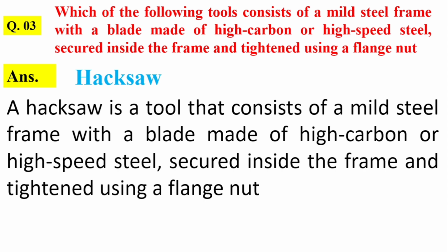A hacksaw is a tool that consists of a mild steel frame with a blade made of high carbon or high speed steel secured inside the frame and tightened using a flange nut, which is tightly fastened, with the flange nut. The frame is made of mild steel, and the blade is high carbon or high speed steel.